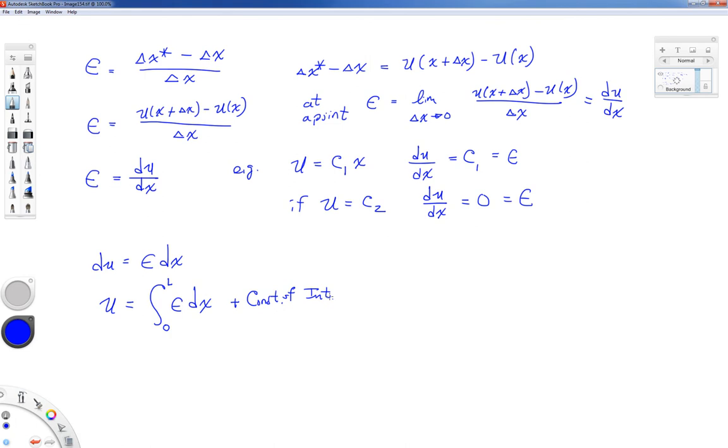Now this term for the displacement u, you see the term on the left that has the integral in it and the term on the right with the constant of integration. The term with the constant of integration is this rigid displacement term. It's what we talked about when we have taken our pencil or our bar and picked it up and moved it. So this is called a rigid body displacement. And this term on the left then represents the displacement of the bar due to stretching of the material.